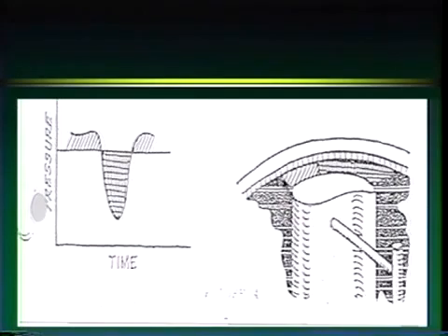On the leading edge of our screen, right here, we've got a positive pressure difference. What that means is that the pressure is higher on the inlet than on the accept side. So pulp fiber will be passing through our screen barrier from feed to accepts.